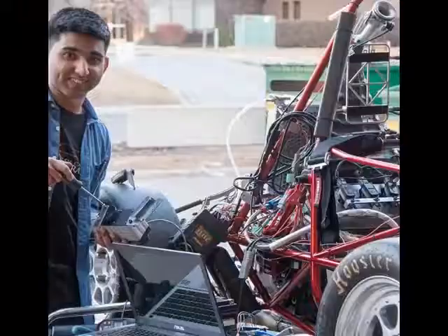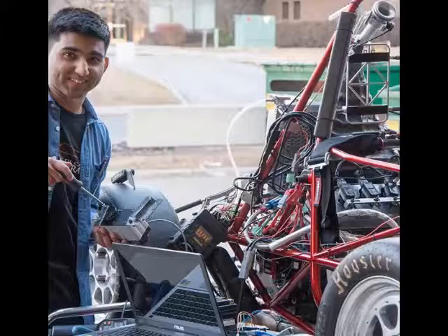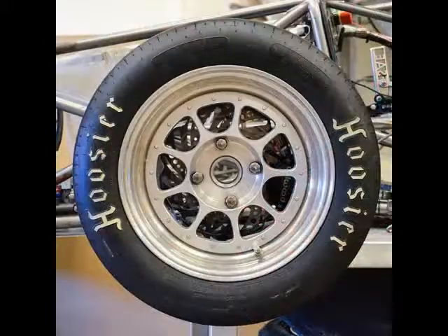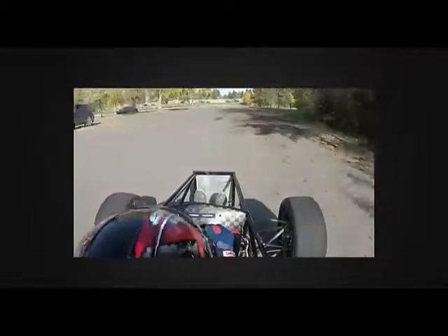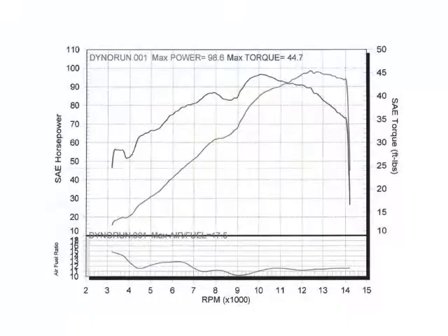portion of time. These forces can be calculated using the formula team's current braking setup, taking into account the specific calipers and rotors used. At high speeds, the car is limited by the maximum torque the engine can generate, which can easily be fit into a curve from dynamometer testing. This can be used as a comparison to account for power limitations.